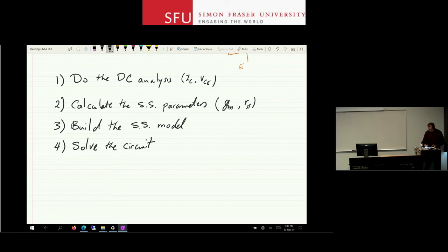Hopefully it will take just a bit of time to solve it. It's usually the AC analysis, if you build it right, is usually simpler than the DC analysis. And then at the end of that story, if you want, you can go and say, okay, so my DC point was 2 volts, and now I have a gain of 100 for a 1 millivolt signal, so the signal goes up and down by about 100 millivolts around that 2 volt point, or you can just keep things separate as they are, right? So the DC and AC analysis part, you report them separately. This is the DC voltage, and this is my AC gain, or input resistance or output resistance, right? And these are the steps that you need to take.